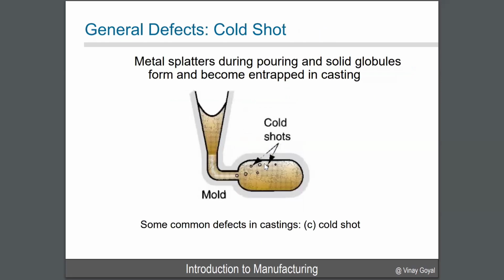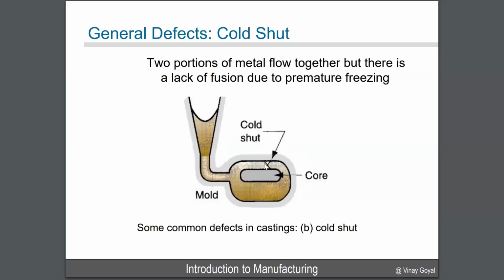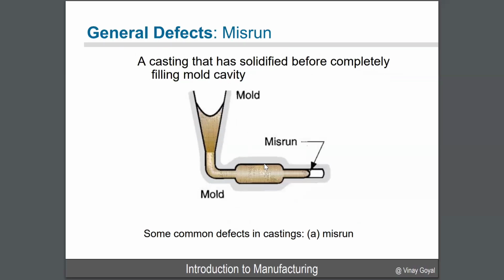The cold shots, similar to the ones I discussed before, you have to evaluate the effects of those stress concentrations. Using finite element analysis could be one way, or testing. Cold shots are very complex issues, and they can degrade the properties quite significantly. But again, all these different kinds of issues need to be evaluated against the intended use, the performance characteristics you're seeking, and whether you can do something about it.